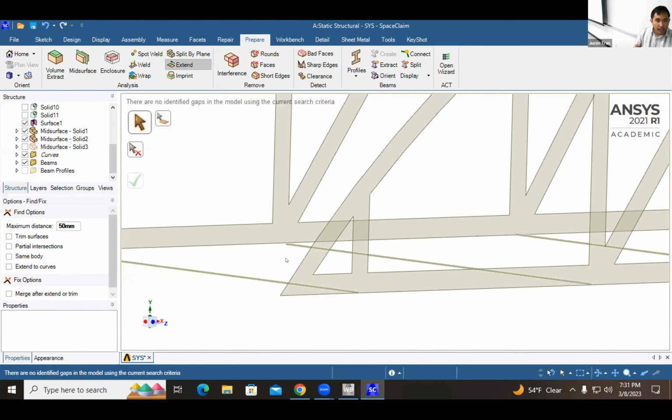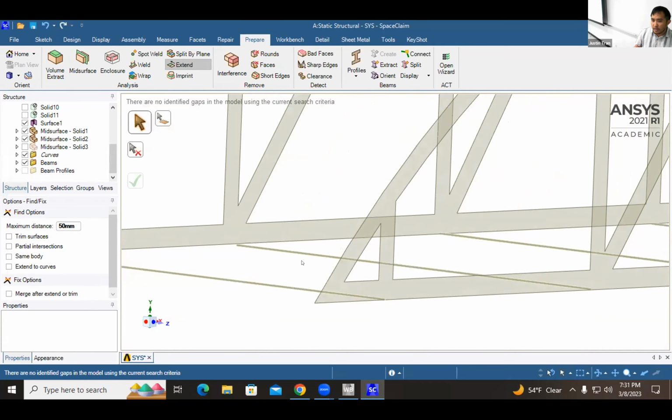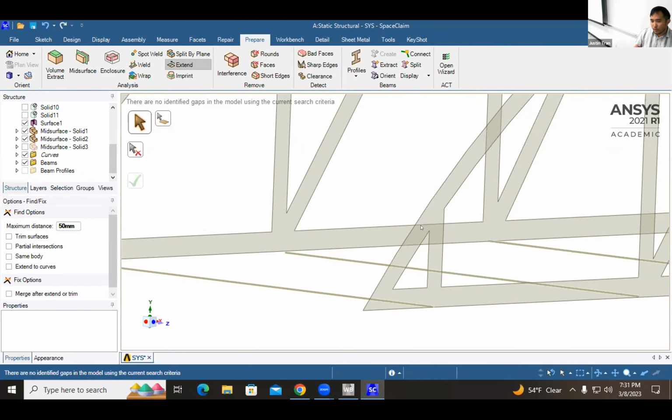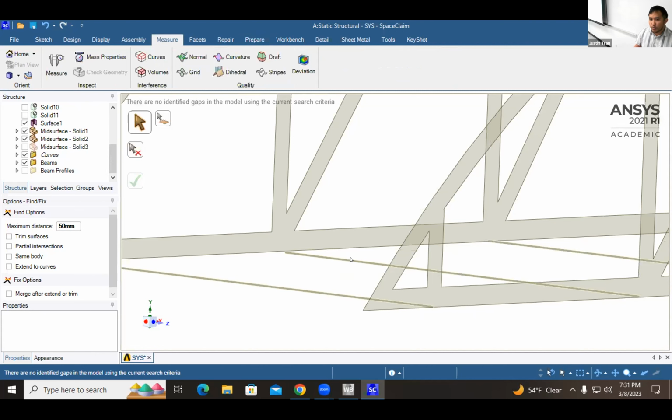Okay. And so the moving up is actually going to take a couple of steps. Even though this CAD model was made a little bit sloppily, we can still make our adjustments clean. Okay. So the first thing we need to do is measure how far off we actually are. Inside SpaceClaim, we have this measure tool. It's useful for a lot of reasons. Sometimes you want to measure certain parts of the geometry that you may have received from someone. Then we're going to click on this measure tool right here.